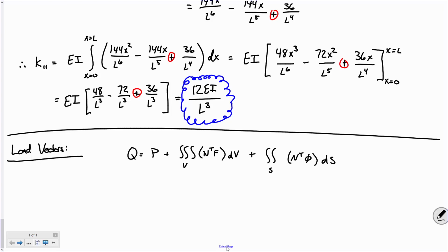Okay. Now, if you want to think of this to try and get some analogy to beam analysis, P is essentially your joint load vector. Those are the loads that are applied directly on the nodes, like what is the force at node 1, what is the moment at node 1, what is the force at node 2, etc. Those are nodal loads. These other two are loads along the member. Now for beams, primarily all we care about are things like distributed loads, triangular loads, and what have you, right? So for beams, what I should say is